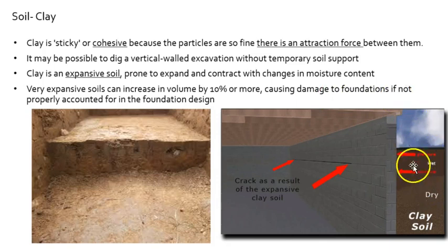So here we have the clay soil that expands when it rains, and it pushes on the foundation wall, and horizontal cracks in foundation walls are often a telltale sign that this type of damage is occurring.